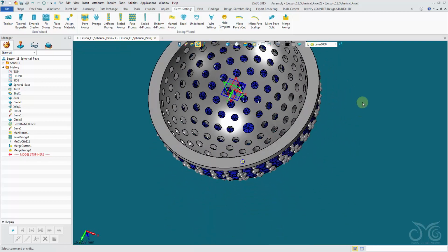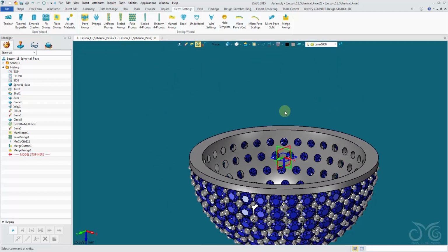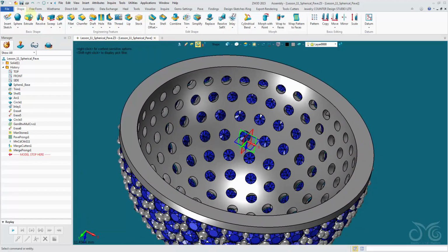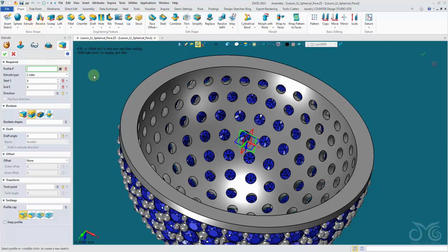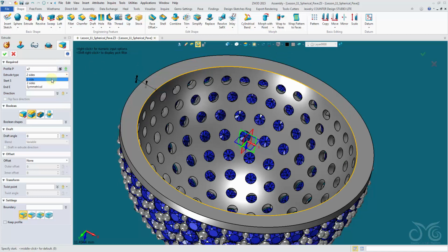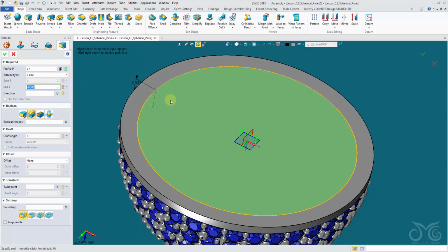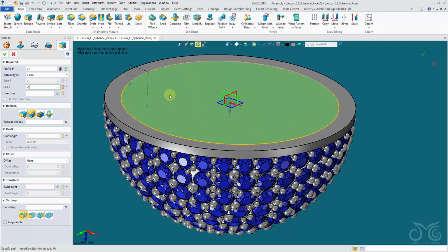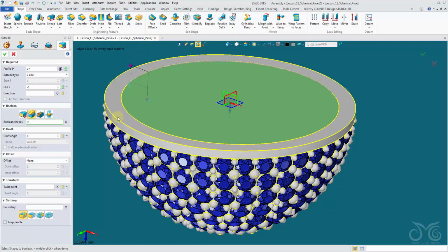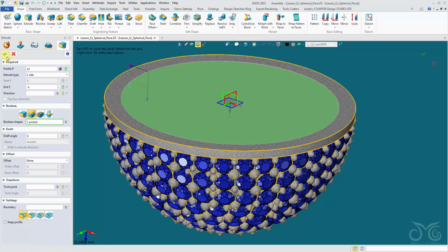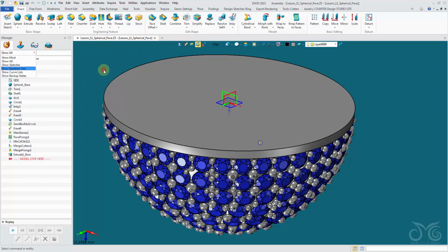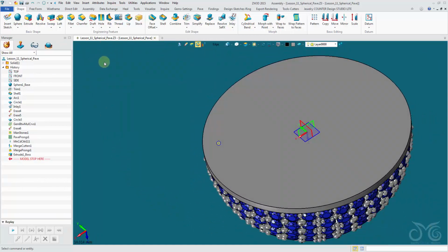Okay, now whilst we're here, let's take a quick look at adding a backplate to our partial sphere. We do this by simply extruding this inside edge one direction. Let's say an offset of -1, Boolean add to our original shape, confirm the operation. Okay, there is our backplate on there now.